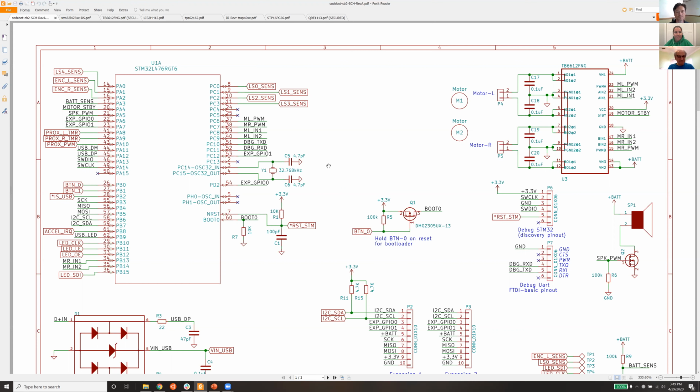Great, thank you. All right, David, Victor would like to know if you flip the JTAG cable and insert, will the student damage the board? On the JTAG, I don't think so. It doesn't look like it would. I haven't tried it, but it would put 3.3 volts on a no connect potentially. So I don't think that would be a problem.